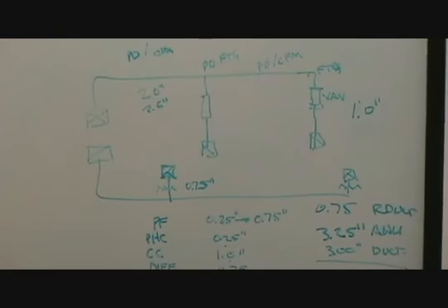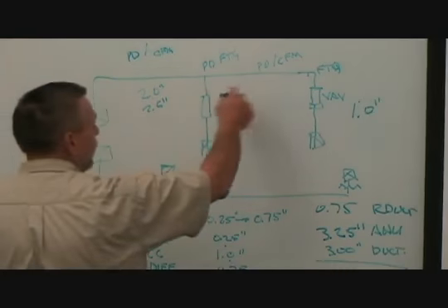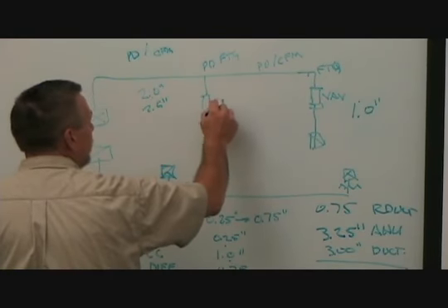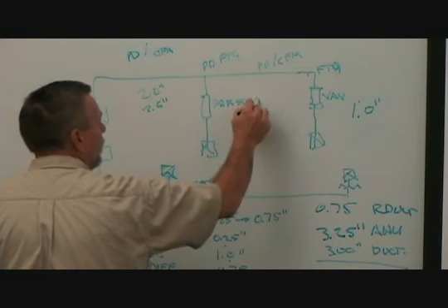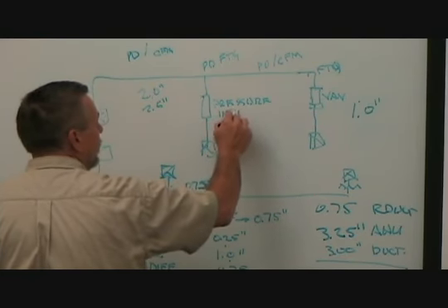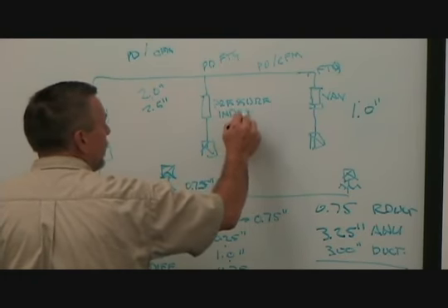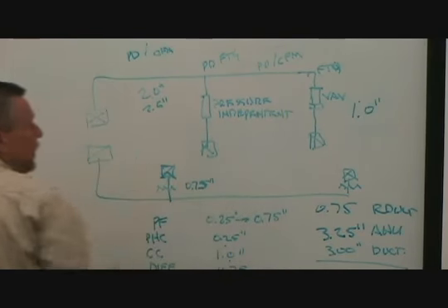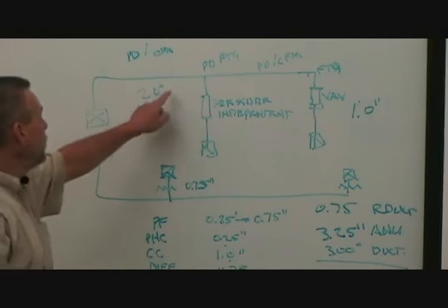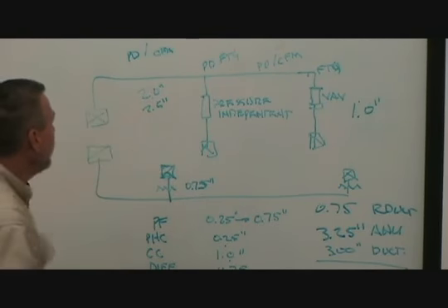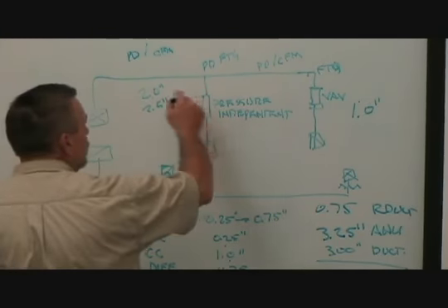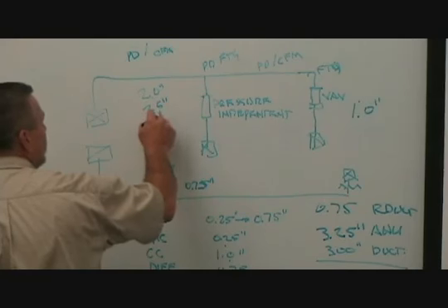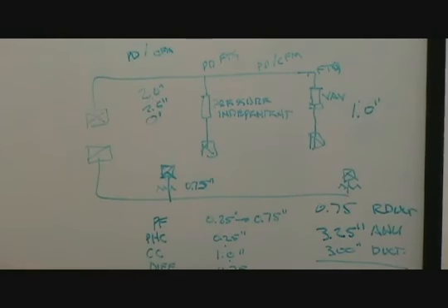On the supply side, it's just like when I talked about a correctly sized control valve. The supply side is self-balancing. These are called pressure independent boxes, meaning that no matter what the pressure is here, and this is going to vary, when all these boxes are closed, this pressure might be at 0 inches because there's no airflow, there's no friction in the duct.